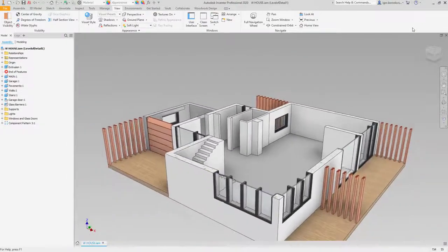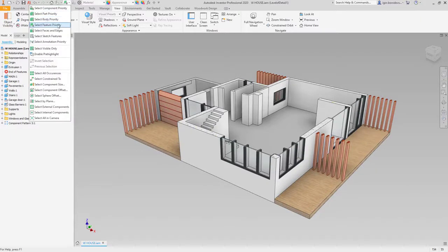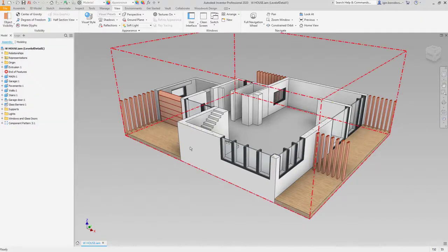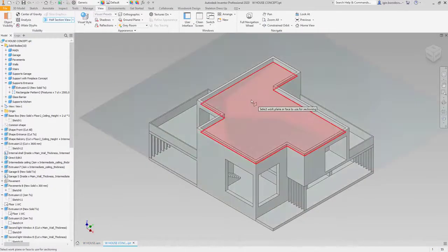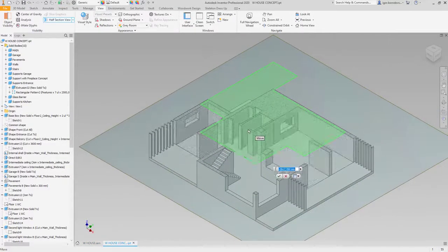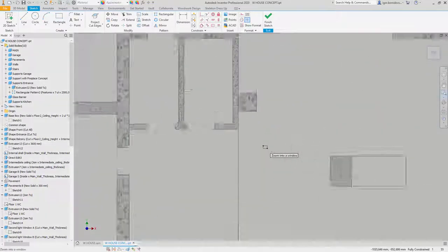Since the house was modeled in a skeleton design way, let's go to the bottom level and add the concept of a kitchen block. It's easy to do this, being in a feature priority, with a double click on any skeleton-driven part. Use section to clearly see the working area. On a new sketch, define a general shape using constraints and dimensions.